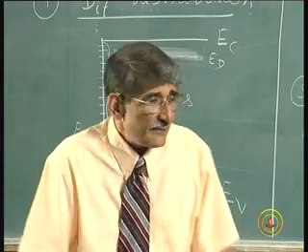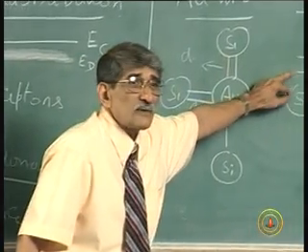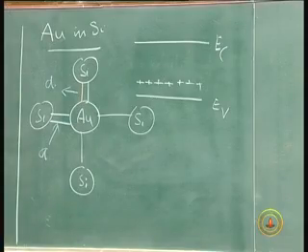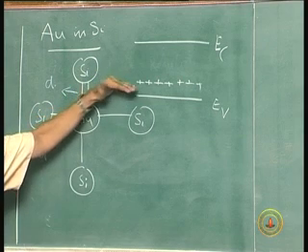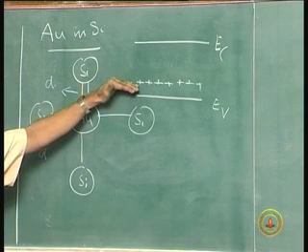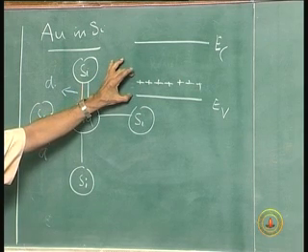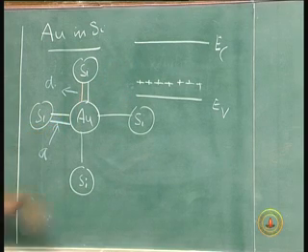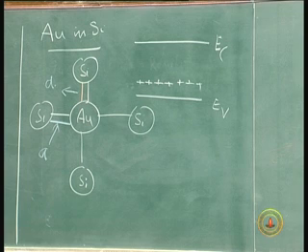Now, I have identified this particular location closer to the valence band because it requires a lot of energy to remove those electrons, because it is like the bond in the silicon. Once you have identified this level very close to the valence band, 0.3 electron volts above the valence band, where will you identify the acceptor level? Will you identify it above or below? That is the only question that I am asking. You have to look at it from the point of view of energy.